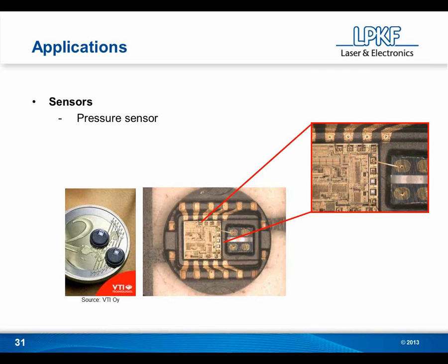So here the semiconductor and the sensors are in this plastic housing, and the only connection between those is direct wire bonding. And the wire bonding lands directly on the plated surfaces on the plastic part. So the entire part consists really only of semiconductor, sensor, and the plastic housing, and of course the wire bonding. But you don't see a lead frame in this part, which is fairly interesting. So this part will then become basically an SMT component when it's done being produced.